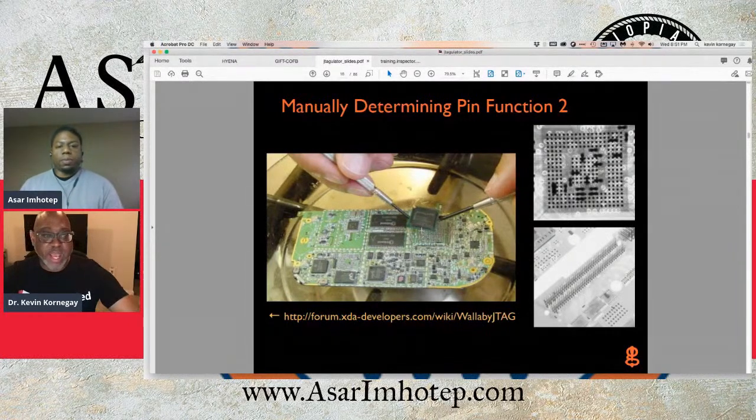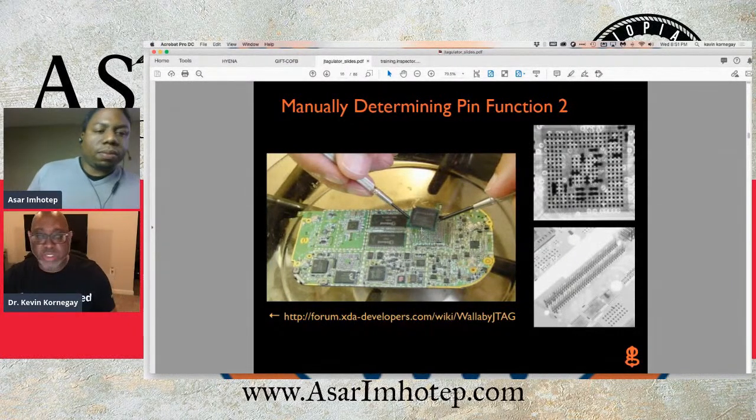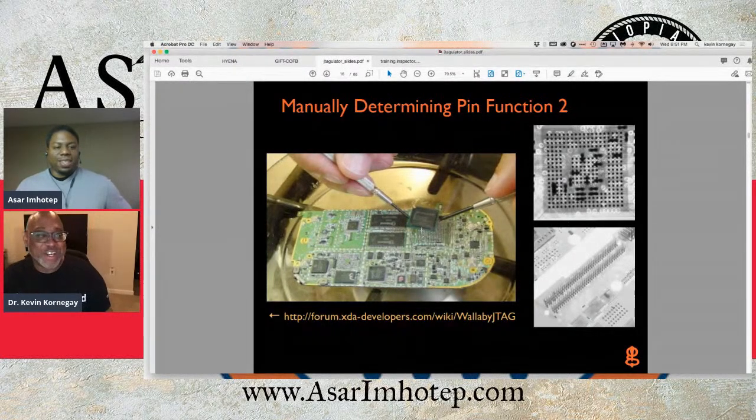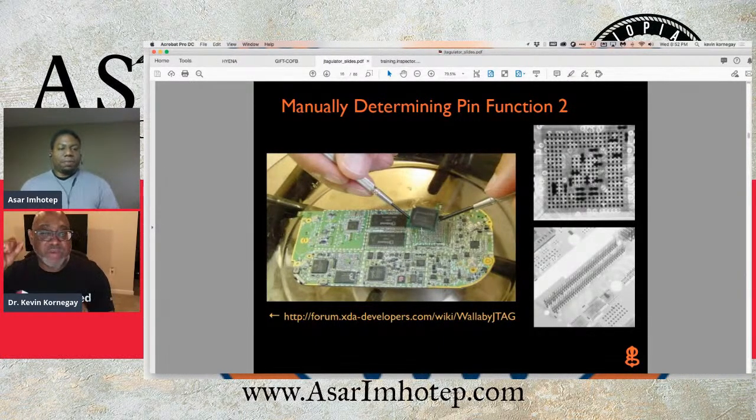So you have a ground mat, because these devices are very sensitive to electrostatic discharge. But in all seriousness, electrostatic discharge will destroy these chips. It's like hitting the chip with a lightning bolt, and that will virtually destroy it.